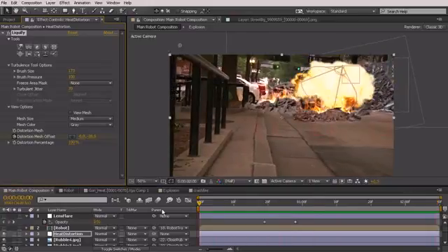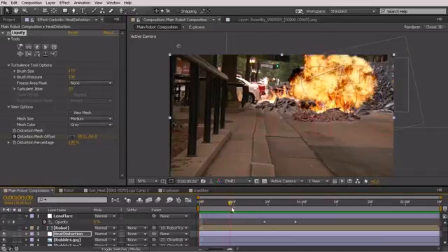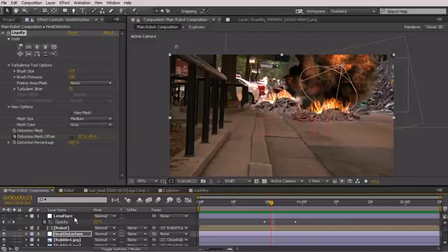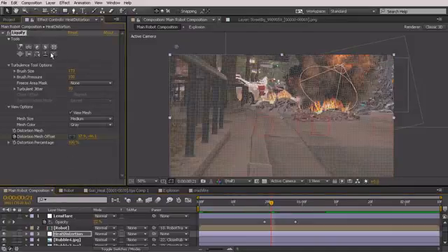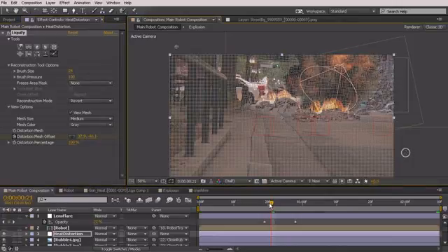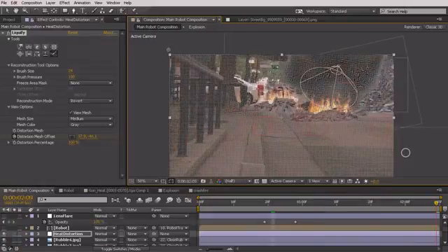So one thing I can do is scrub over to the point where I start to see that black line flicker. And then we'll grab our heat distortion, turn back on the View Mesh, and you can use this tool, which is the tool that's going to basically put everything back as it was. So by selecting that reconstruction tool, we turn down your brush size a little bit. You can come in here and just maybe paint along that edge. And then let's see if that looks odd.